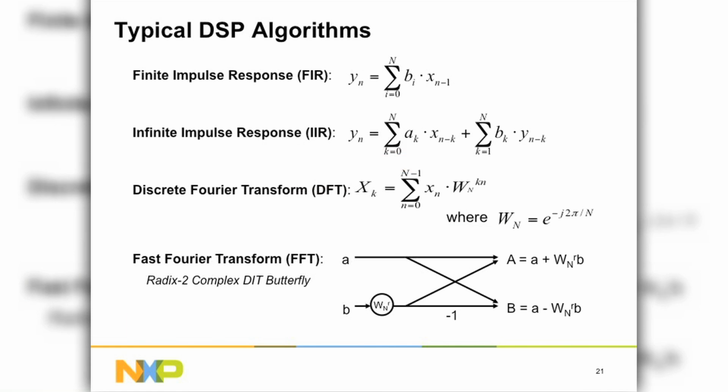Okay, for those of you who are interested, or at least want a quick understanding, a very broad brush on DSP. DSP processors have traditionally been optimized to do FIR filters, IIR filters, and FFTs. In fact, an FFT used to be the standard benchmark to compare different DSPs, or how fast you could do a single cycle multiply accumulate for the FIR filter. What these all have in common, as you can see, is a multiply of a coefficient and a data value, and a summation or accumulation of the data to the output.